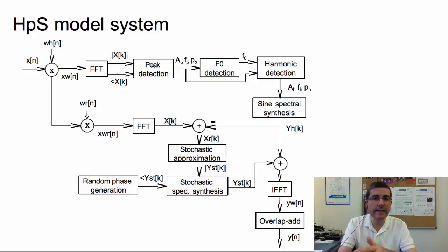So we can put it together into an analysis synthesis system, and it's very similar to what we saw before. We start from the signal, we compute the FFT, we find the peaks, we find harmonics, we synthesize them in the frequency domain, and we subtract them from another spectrum of the original signal, recomputed to be able to subtract it.